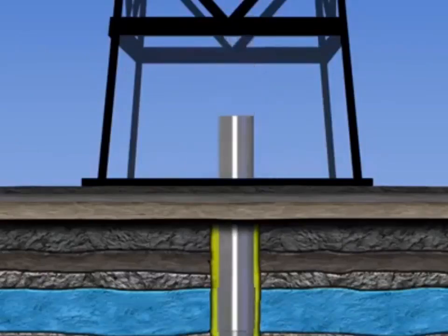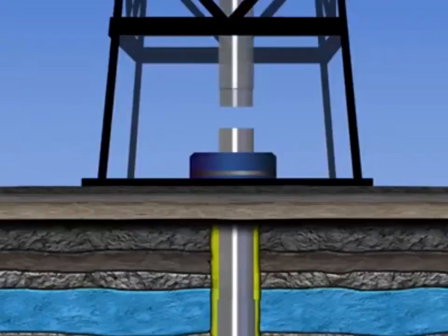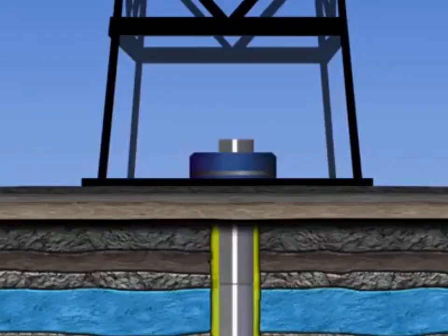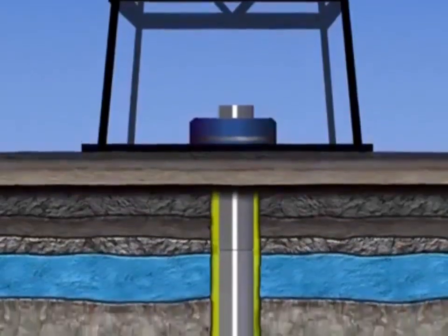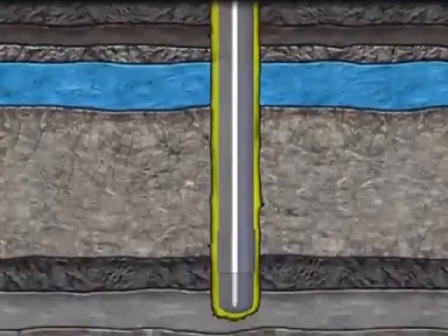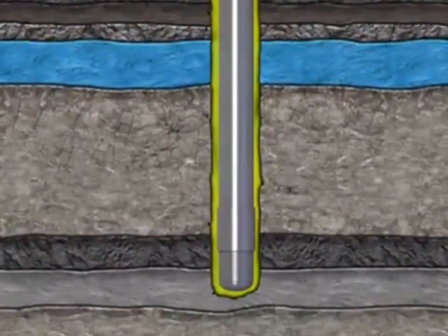The selection of the casing grade depends on several variables, including the size of the hole, the rugosity of the drilled hole, the expected pressure of the flowing hydrocarbons, the H2S content, as well as economic considerations. Once the entire weight of the casing string is solely suspended by the hangers, the casing is considered laid in place.